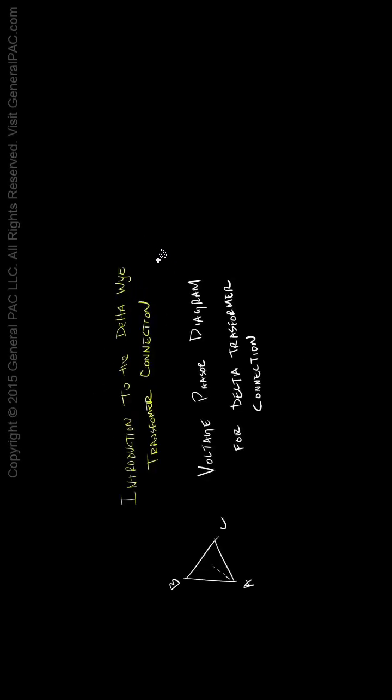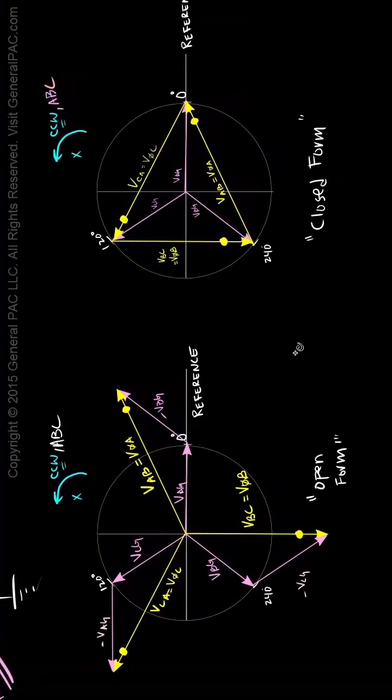Introduction to Delta-Wye transformer connection, part 6D. So this is where we left off in part 6C. In this part, we're going to explain what this means and how this works. Now we said in our last video, this is often referred to as the open form phasor diagram, and this one is referred to as the closed form phasor diagram. So open form versus closed form phasor diagram have their own advantages.